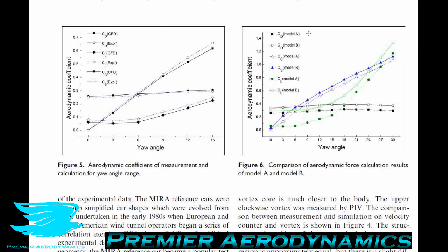For the lift coefficient, when we increase the yaw angle, the lift coefficient increases in a kind of quadratic fashion. Around 0, the 0-degree yaw angle, we get the lowest lift coefficient. And as we go up to 30 degrees, the lift coefficient increases quite a lot, to like 1.3, which is actually phenomenal when you think about it, because that's airfoil territory. Something which isn't supposed to be producing a lot of lift, at least not by design, is producing as much lift as something that is designed to produce lift, which is an airfoil.